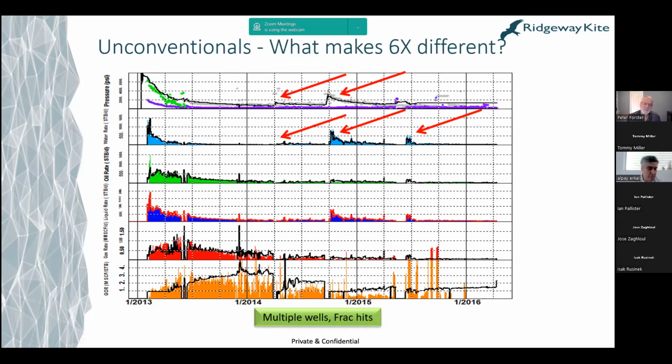If we look at the plot of what's going on at that parent well, this top graph here is the pressure, the next one is the water saturation. If we plot those characteristics against time, we can see where we have high pressure at the beginning, where the fluids are being pumped to fracture it, and then we've got the depletion, and then later on we've got frac hits which come in and cause a bump in the pressure and in the water production.